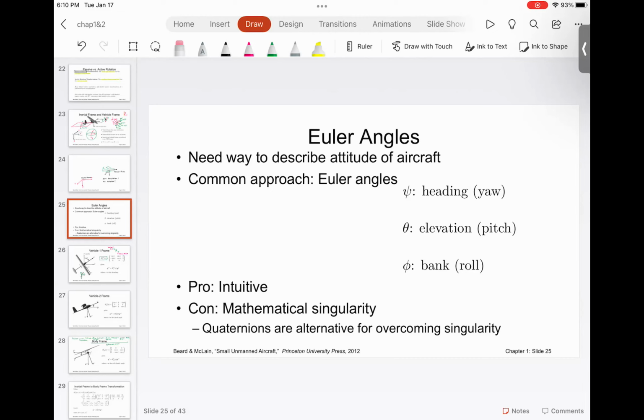The problem with Euler angles is actually quaternion multiplication. The math may seem complex, but when we try to use it in a recursive application like computer algebra, or if we try to implement that on an embedded system, propagating quaternions is easier because it's less matrix calculation than propagating a direction cosine matrix or Euler angles.